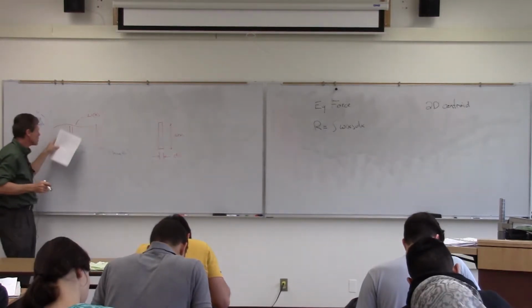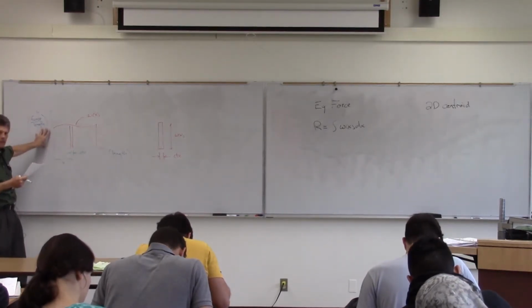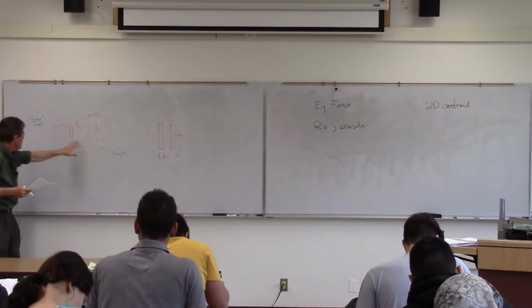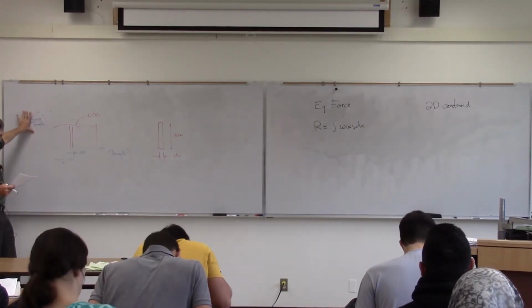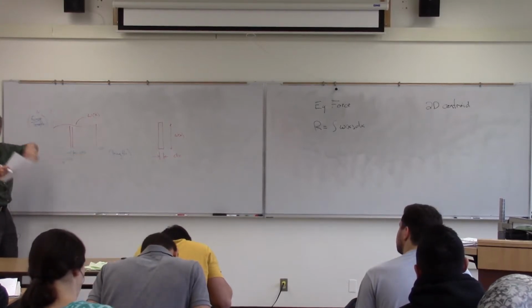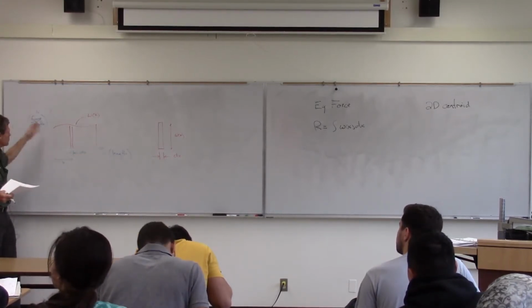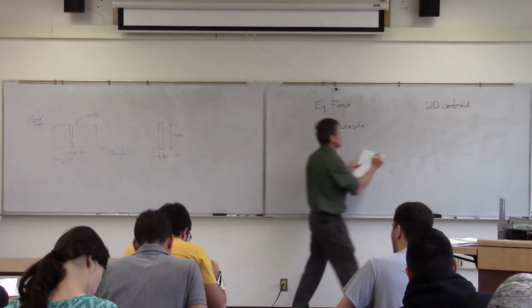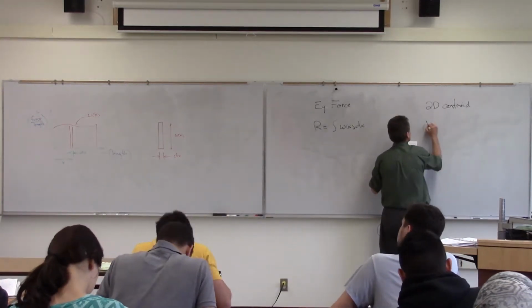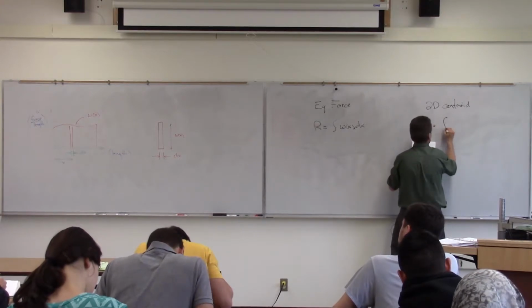So it's the area of this, but now it's a load area because we have it in terms of load intensity times length. Now note, if this was rectangular, this would be force divided by length times length, which equals force. The two lengths would cancel each other out, which is the same thing that we just got done doing in terms of our centroid.